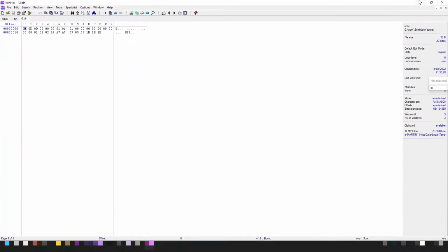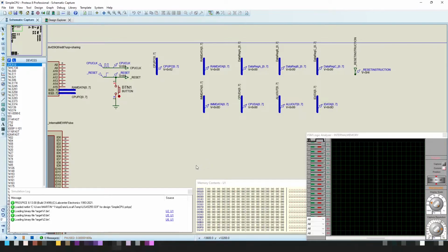So we know that we have started getting instruction data. And what we would want to see eventually, if I keep on clicking through and advancing the CPU PC, is that the data address register here should contain the value of D, which is 13. If I click once more and a few more times, there we go. The debug value of the address register has changed to 13. And then the program counter is 4, and so on and so forth.